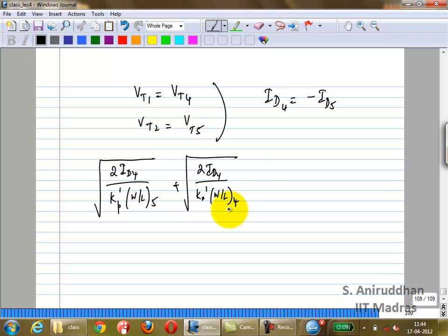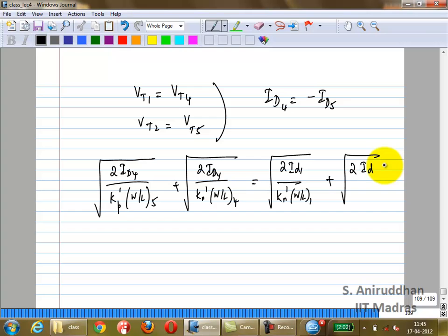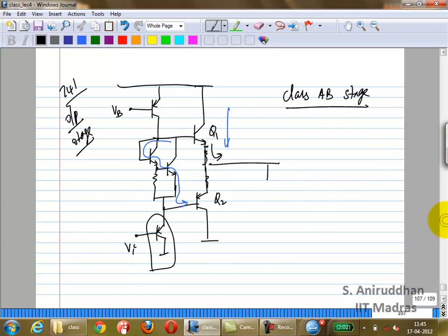So this is the left hand side. What do you use here? Do you use ID2 or ID1 or what do you do? Ideally, in reality it should be ID2. What we'll do is we'll assume that we are doing the case when V out equals 0. Therefore ID1 equals ID2 equals minus ID1. If you remember, we analyzed the 741 output stage, found out the bias currents and so on, but we did it at the case when V out equal to 0.